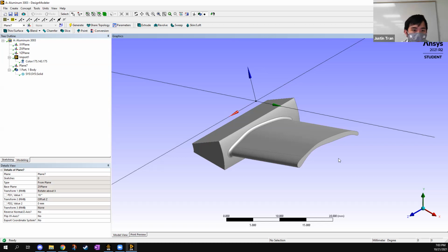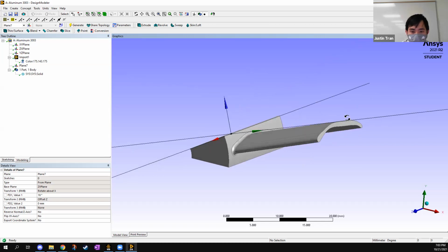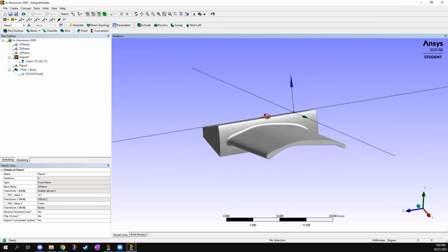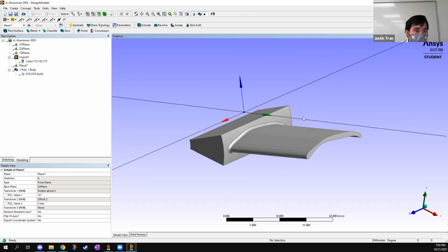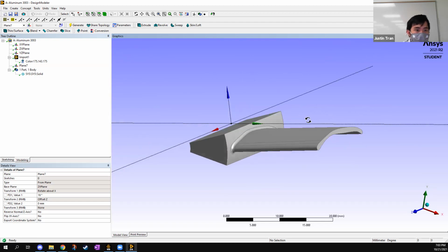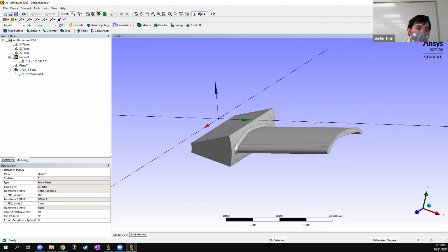Yeah. So basically what I've been looking for is the logic behind your finite element decisions. First of all, like what we're talking about right now, how you're going to choose to model the loads, where you are going to put them, and does that make physical sense? When you're going to the meshing, do the meshing settings that you chose make sense? Did you have refinement in the areas that make sense? Did you use the right element order and element size?